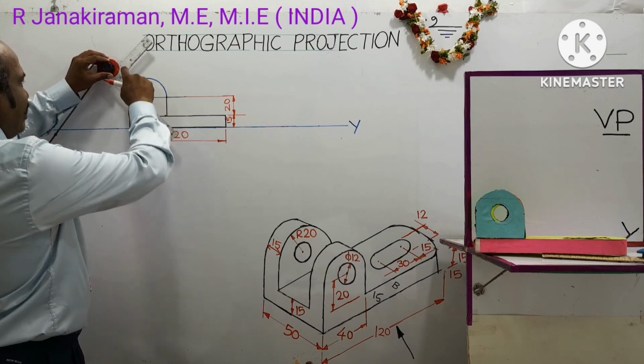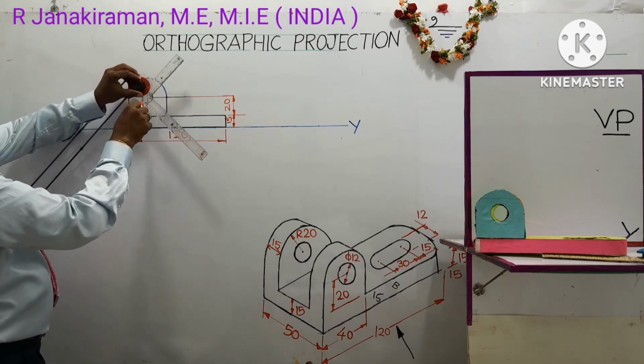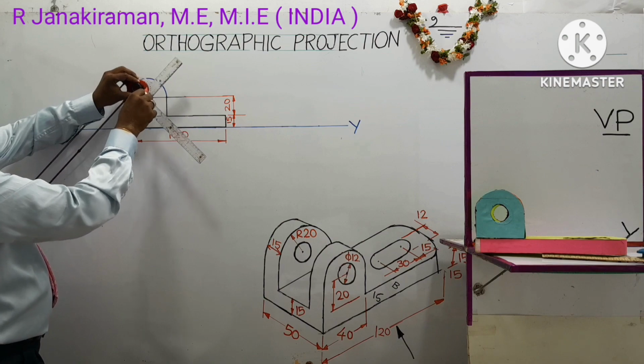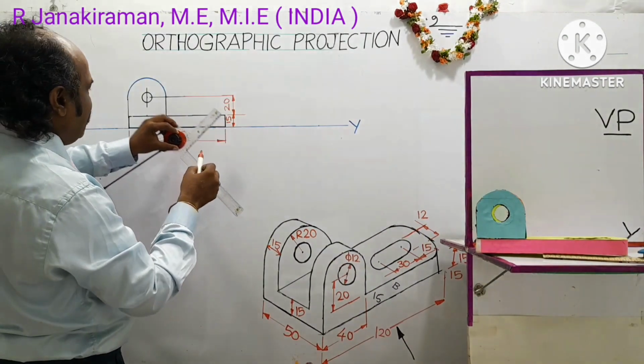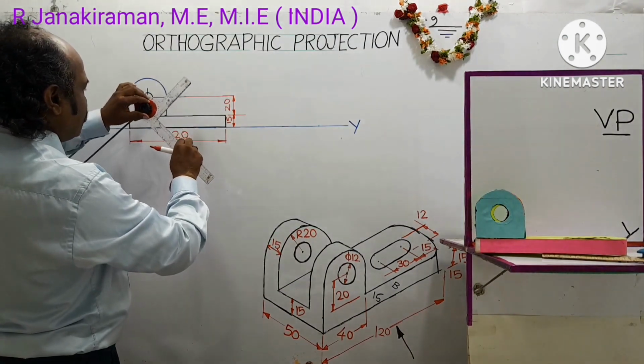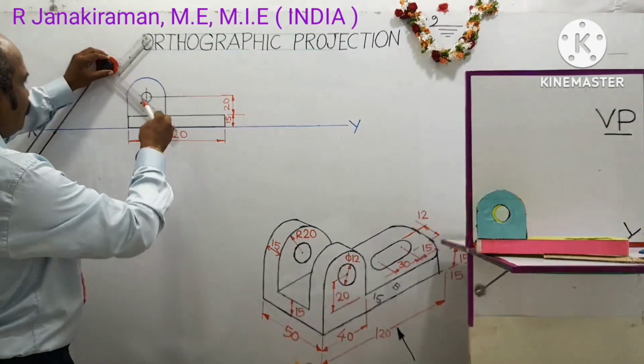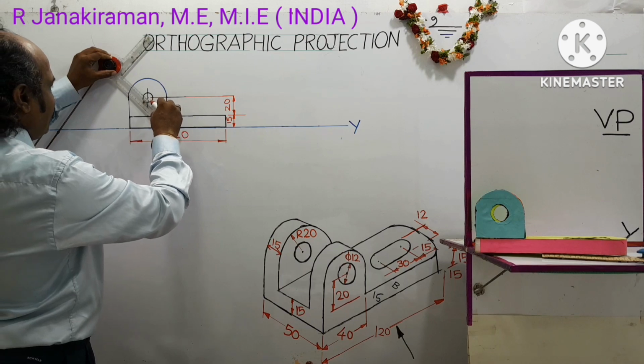After tilting, the protractor arrangement is given. With this marked point as reference on the drafter scale, one line will be there. That should coincide with the 45 degree angle. Rotate the nut clockwise, and the scale will be positioned like this. So draw an inclined 45 degree line, called a leader line.